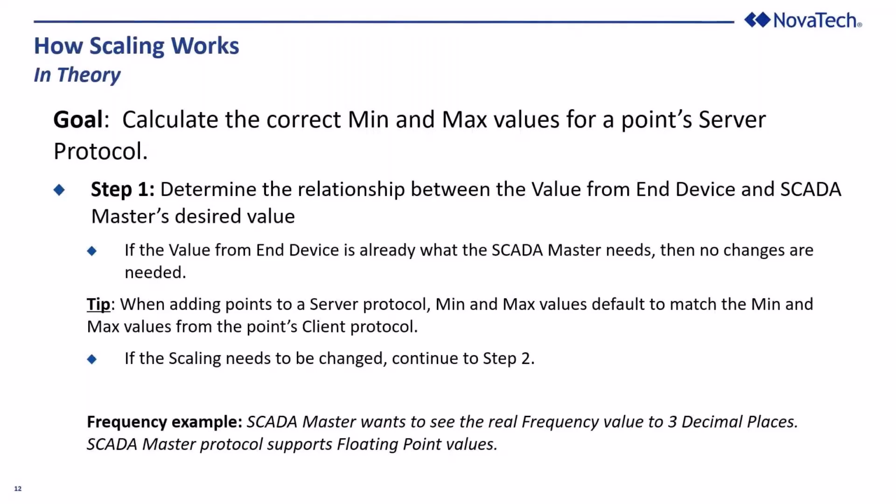In the frequency example we talked about earlier, we're going to assume that the SCADA master wants to see the real frequency value to 3 decimal places, and the SCADA master protocol does support floating point values. We already determined that the device measuring frequency will only transmit an integer to the RTU. So we'll step through some equations to show you how you can get that measured value all the way up to the SCADA master.